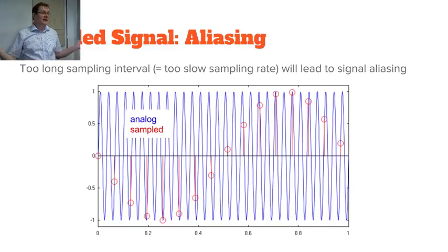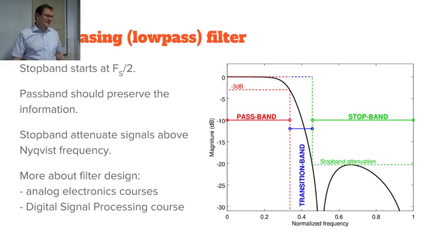So to prevent aliasing, you need to remove or reduce enough of those high frequency components so you can sample the signal as it is, or go to a higher sampling rate. But usually you cannot. And the anti-aliasing filter is simply a low-pass filter to reduce those unwanted frequencies.